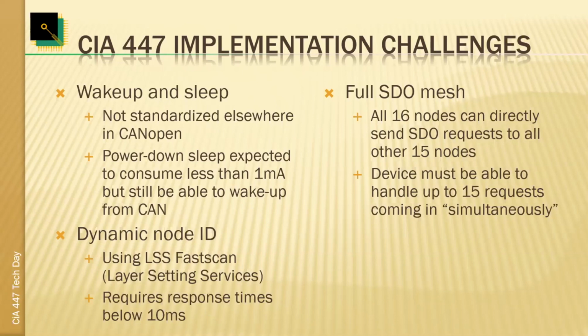So if you imagine a police car and you're already sitting in the car taking a break, and now you have to go out on a mission, and you press the button to switch on the blue light. Well, if that is the first action and the entire bus is asleep, then if everything goes well, it can happen that within a few hundred milliseconds your blue light goes on. But in the worst case, if, as I said, one of these delays is there, a slower node, or nodes are not permanently present, suddenly such a startup could take 2, 3 or more seconds. And that's, of course, irritating.